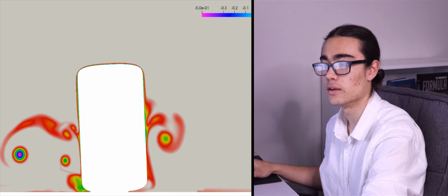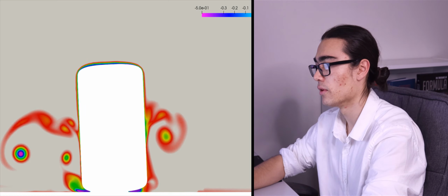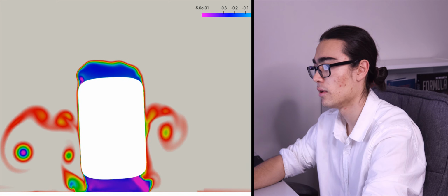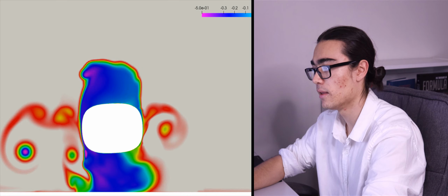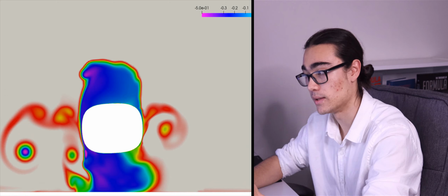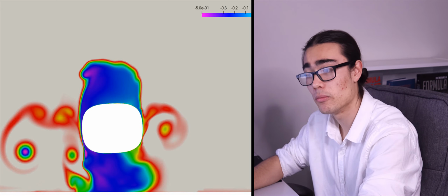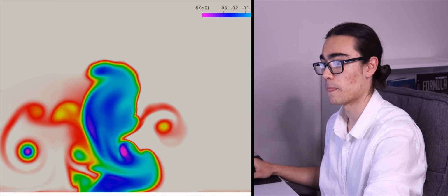Okay, let's continue. We've got progressively more squirt, and we're back behind our tire. Interesting little effect there with the straight vortex, you can see. This is indicating perhaps some attachment, or a bit of attachment somewhat around the back of the tire, pulling the wake outboard a bit, but we'll have to check with some other contours. And we have that. So now we should really compare our two cases and see the major differences in the